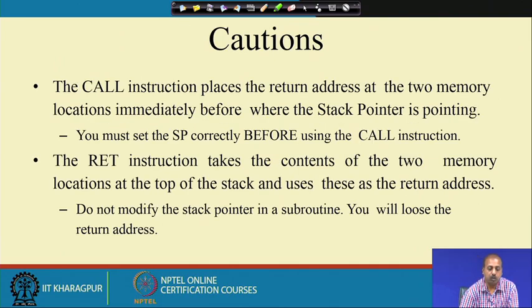There is a caution: the call instruction places the return address at the two memory locations immediately before where the stack pointer is pointing. So, you must set the stack pointer correctly before using the call instruction. The 8085 designers made the call instruction execution such that the program counter value will be saved onto the stack, but it does not do anything regarding stack pointer initialization.